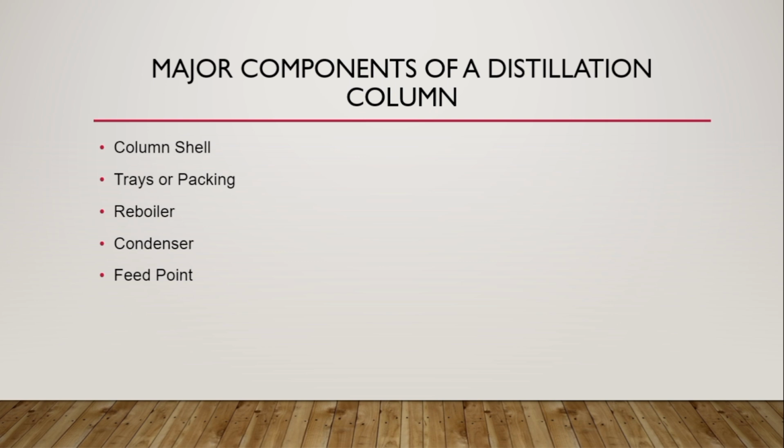So much English. The reboiler. This is where the reflux action comes in, especially for the continuous distillation column. The reboiler basically boils the liquids that come down as condensates. We will get to make more sense of what I'm saying very soon.